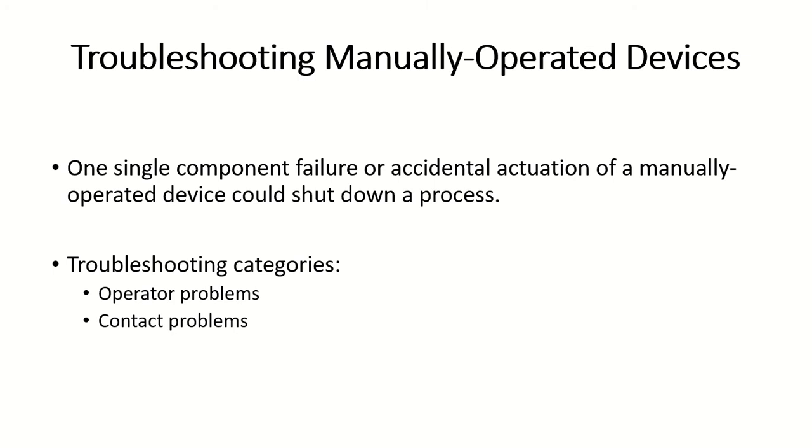So make sure that your connections are real good connections, nice and tight, and that none of the contacts are corroded. That's something you can typically just visually look at and spot without having to turn anything off or on. So just be really careful when troubleshooting, because you could potentially shut down an entire process.